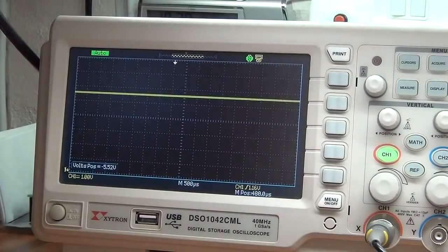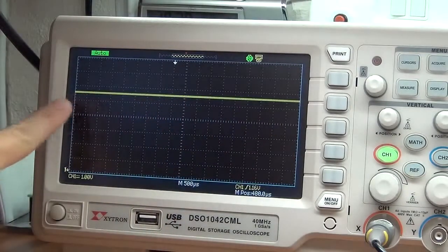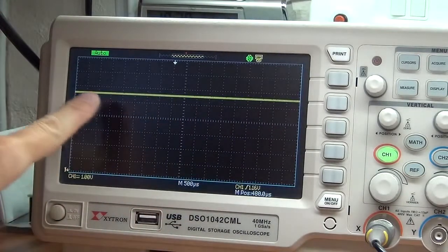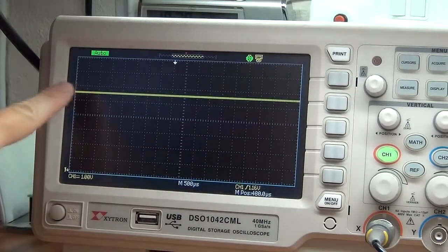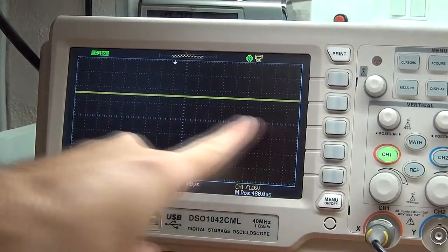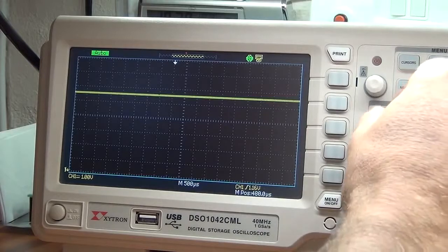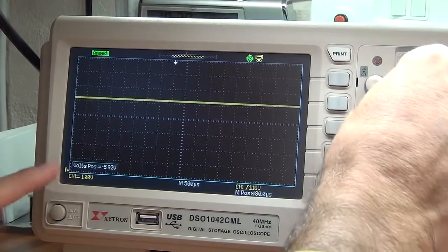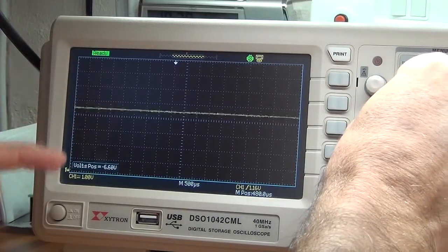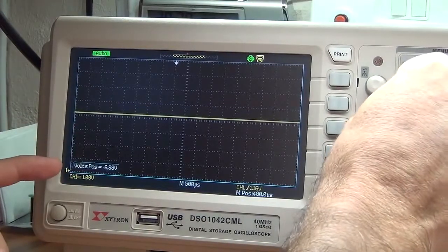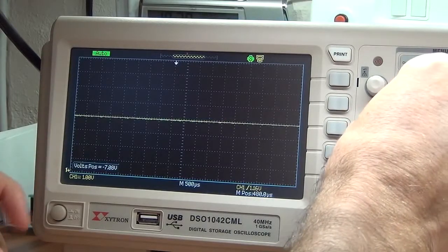As I showed you on that diagram, this is what a multimeter would represent as a reading if you put it across that battery. It's a straight line because the value is not changing, so it's simply a straight trace across the screen. Now as I bring that down, you'll see there's a volts position, and it's showing negative because in essence the 0 point is being moved down as I adjust the vertical position.